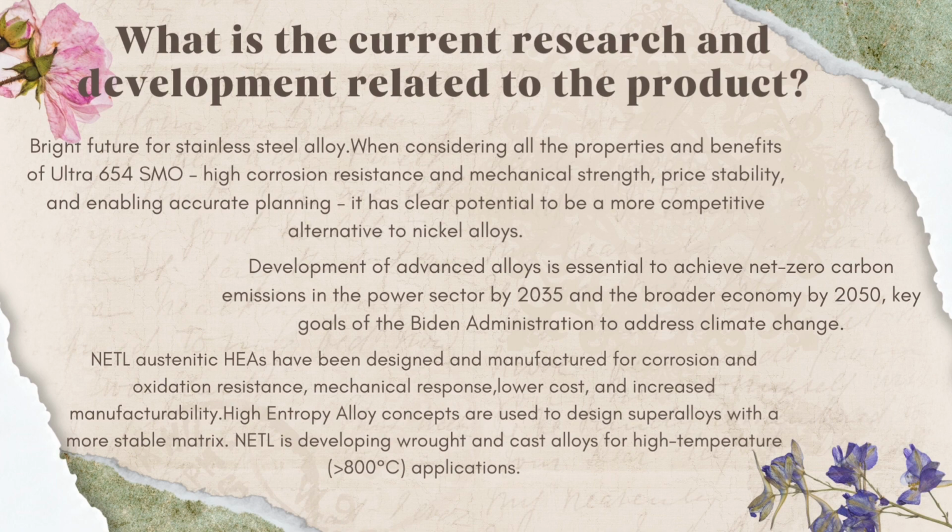NETL austenitic HEAs have been designed and manufactured for corrosion and oxidation resistance, mechanical response, lower cost, and increased manufacturability. High entropy alloy concepts are used to design superalloys with a more stable matrix. And NETL is developing wrought and cast alloys for high temperature applications.